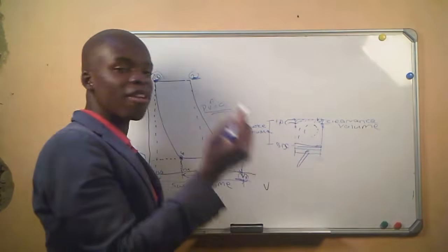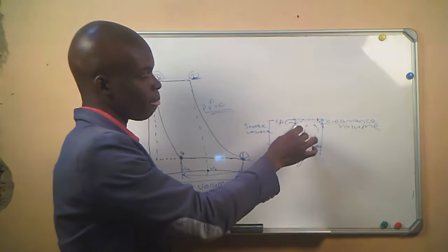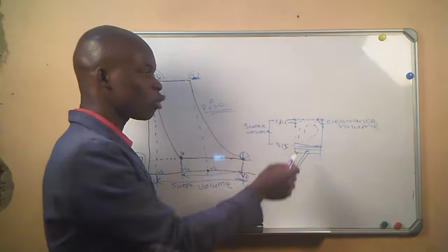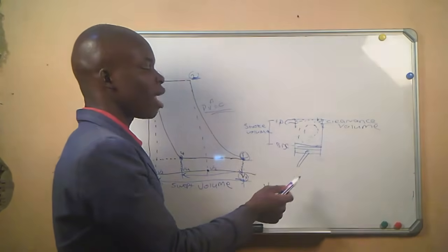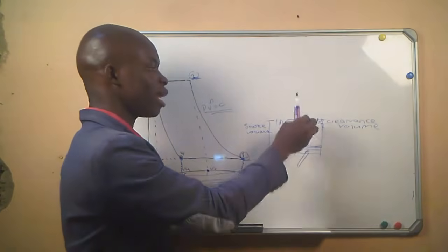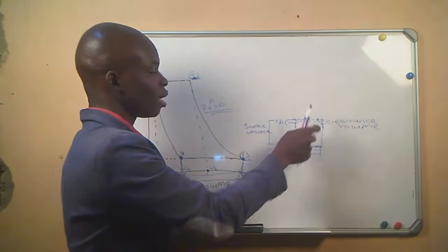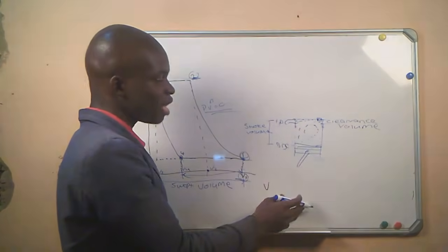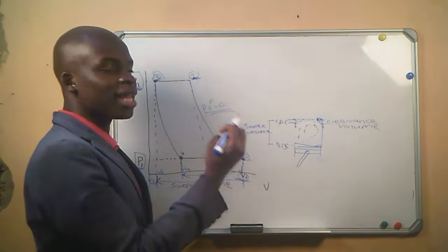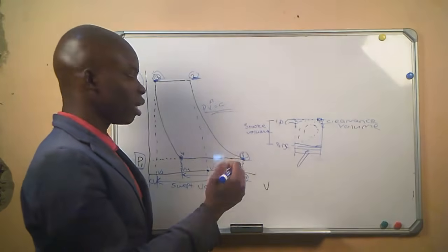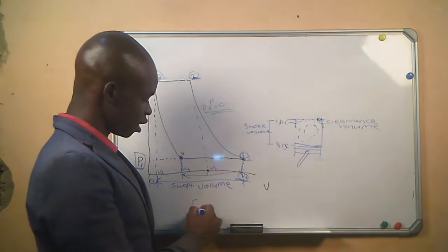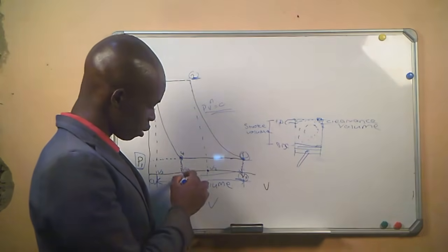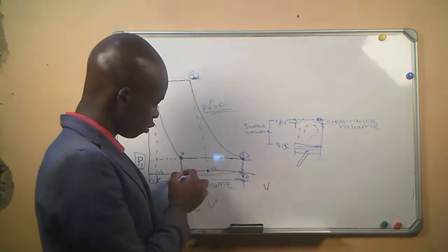So we already have air in the system, the air that was compressed in the clearance volume, and then the piston moved down, that air was expanded, and then after the valve opened, that amount of air that will come into the system is what we call the effective volume, which is from V1 to V4.